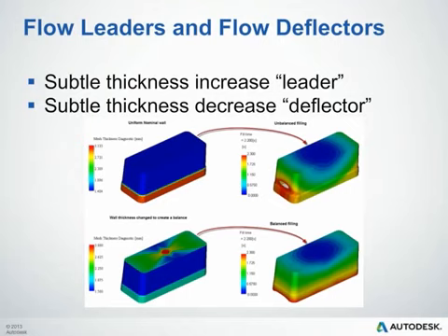Flow leaders and flow deflectors can also be a useful tool for you. Flow leaders are local increases in your nominal wall thickness, whereas flow deflectors are the opposite. They're local decreases in your wall thickness.